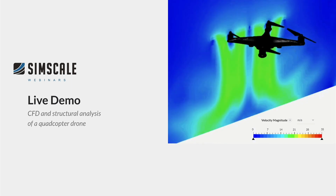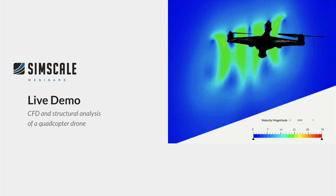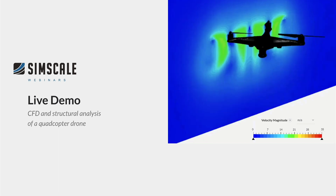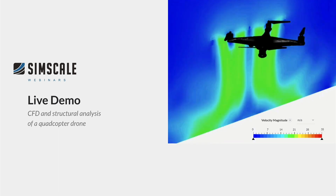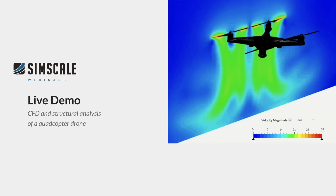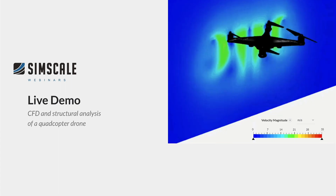So for the CFD, we're going to be looking at a hover case. Now, hover is one of the most important regimes for helicopters and multi-rotors. This is because at hover, it has the maximum power requirements. For UAVs and drones, the hover in ground effect, or in confined spaces, is especially important because they're designed to